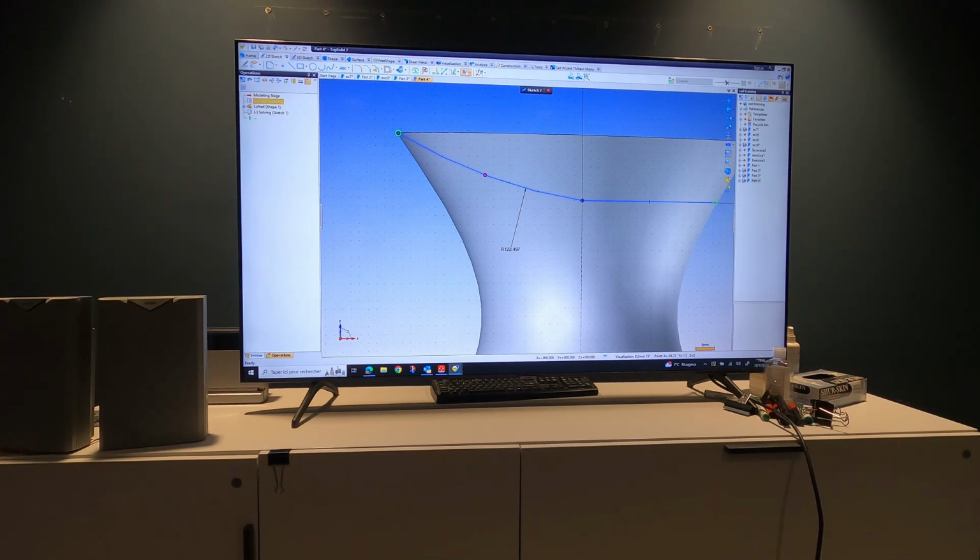Try it. I gave it a range, so now I can cut. But you understand that you have to remove the radius before touching the line, because of tangency. And I think it's giving you the error now. Tangency affects the radius.